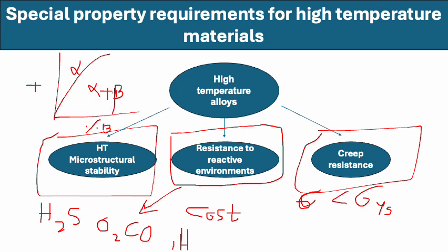below the solvus temperature, because you might use this precipitate for hardening. But if your operating temperature is here, then even if you started with a two-phase material that had all the strength, as soon as you go to this temperature, you will dissolve the precipitate and you lose the property. So you should choose the material such that the solvus temperature is above the intended operating temperature.